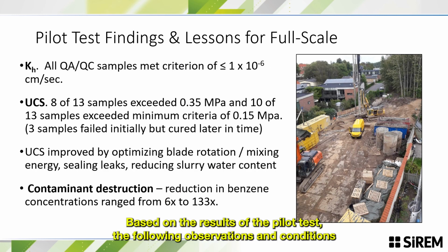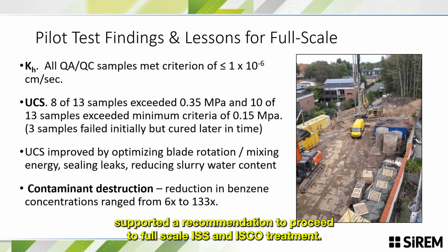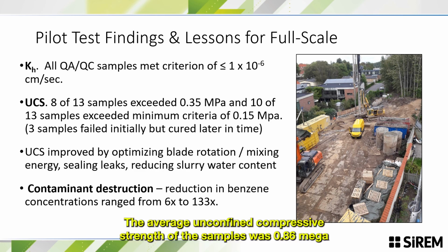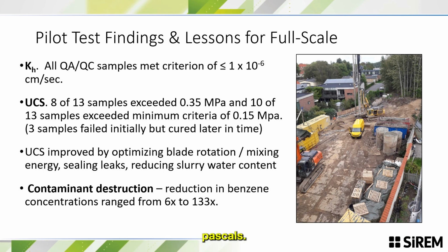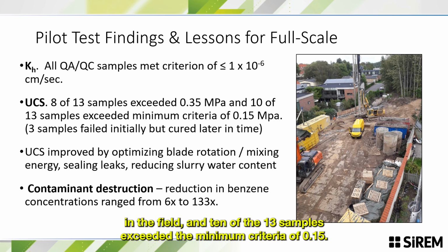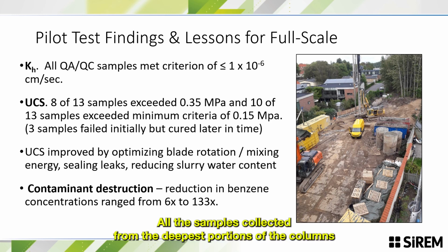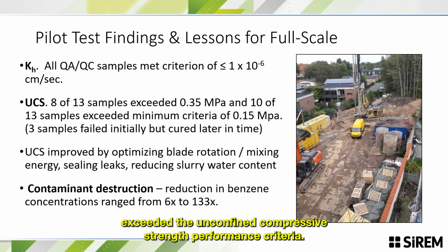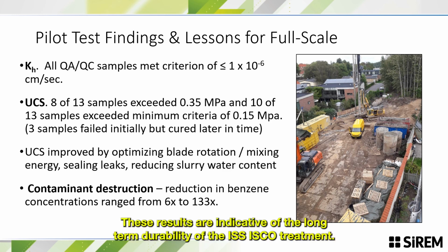Based on the results of the pilot test, the following observations and conditions supported a recommendation to proceed to full-scale ISS and ISCO treatment. The average unconfined compressive strength of the samples was 0.86 megapascals. 8 of the 13 samples exceeded the criteria of 0.35 megapascals in the field, and 10 of the 13 samples exceeded the minimum criteria of 0.15. All the samples collected from the deepest portions of the columns exceeded the unconfined compressive strength performance criteria. These results are indicative of the long-term durability of the ISS-ISCO treatment.